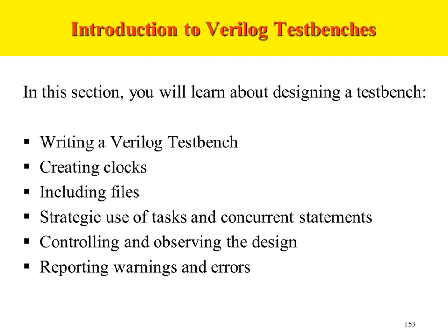The way it works is, you might have used various boards, for example, in your electronics labs or embedded labs. To test the logic on the board, you apply the inputs to the board using signal generators or some other mechanism, and the board will generate certain outputs. Those outputs have to be monitored, using an oscilloscope, a digital logic analyzer, multimeters, or other mechanisms.